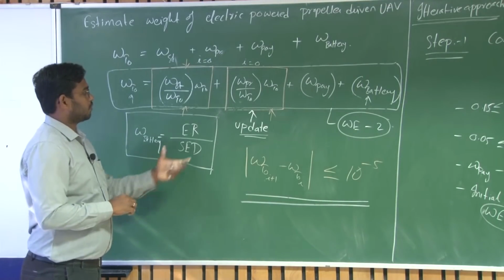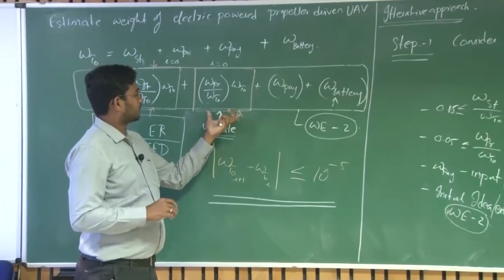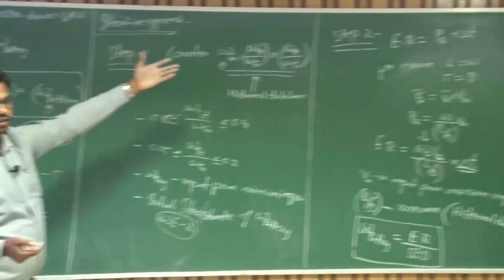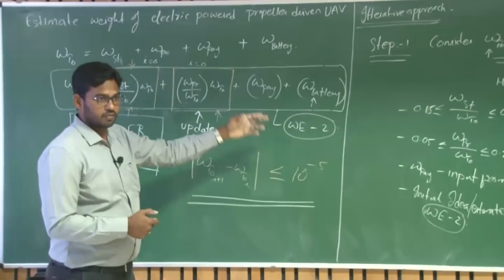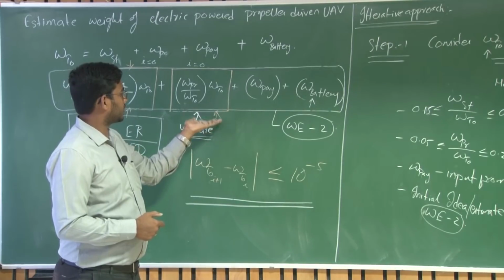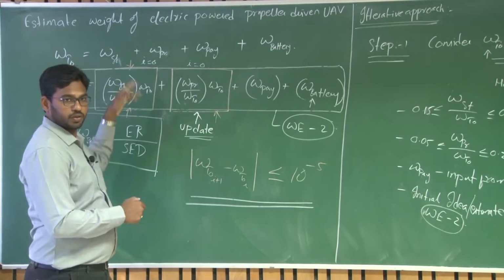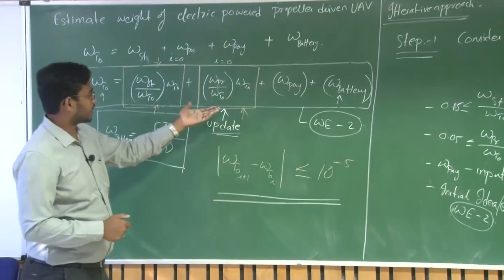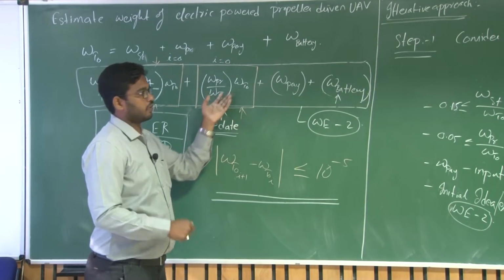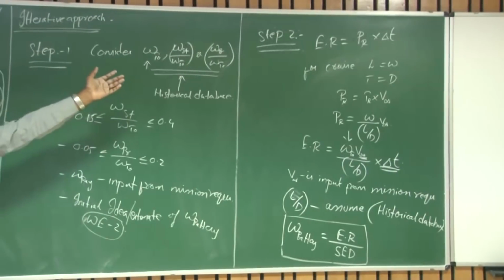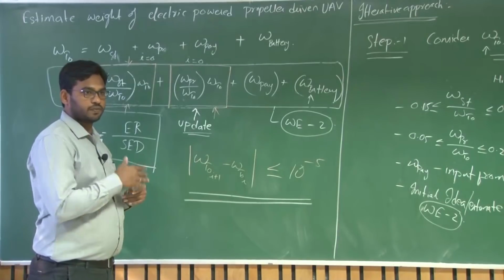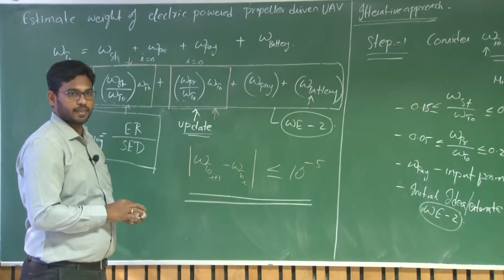Okay. But see, you can again ask, the power requirement again changes since the takeoff weight changes here even after the second iteration. But we are considering the power plant, whatever we are selecting here by this algorithm, as a power plant that can operate at 50% of the maximum requirement, right? So this will take care of, say, a 20 to 30% increase in the power requirement.